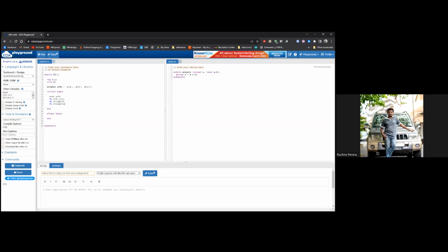Okay, good. This is our basic circuit. And now I am going to use one always block as well, just to show you how the simulation works. I'm going to define my always block like this. It is always, and then we have the at symbol, and then within parentheses we have this star symbol. That means this line is telling the simulator to change this event every time. Basically this will run every time.